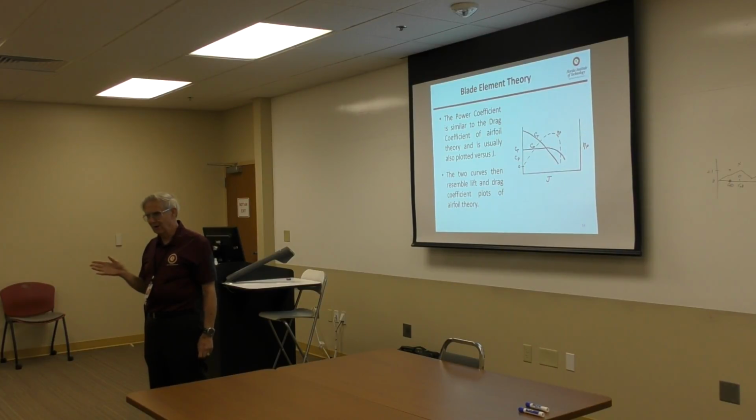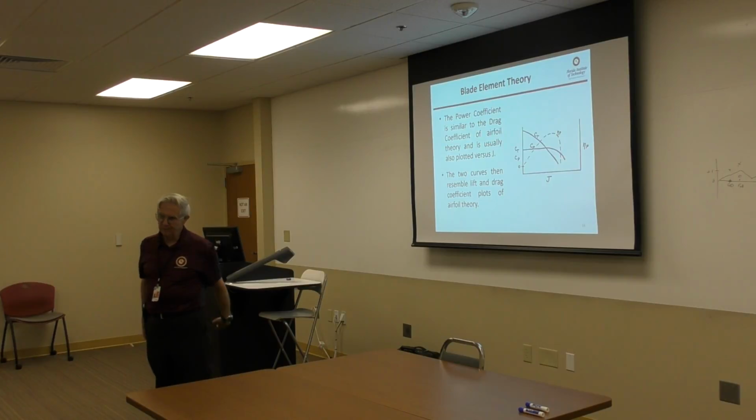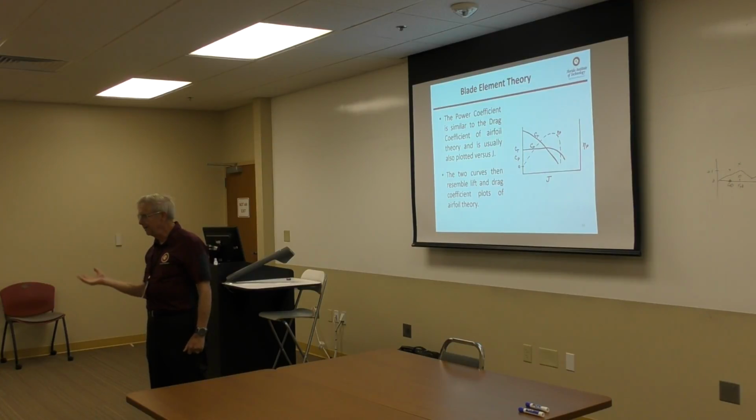So if ND are the same, then it only has efficiency at one airspeed. Let's use the Warrior as an example, since that was a question I had. The propeller on a Warrior is only most efficient at one airspeed. Every place else in its flight regime, it's off max efficiency.